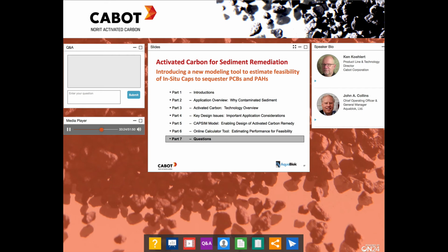That's a good question. Typically, when we talk about in situ treatment, we're talking about relatively lower energy environments, for that very reason. If you're trying to use activated carbon in a capping scenario or an in situ scenario where you have relatively high flow rates, or it's a flashy situation, it's probably not going to be as applicable.